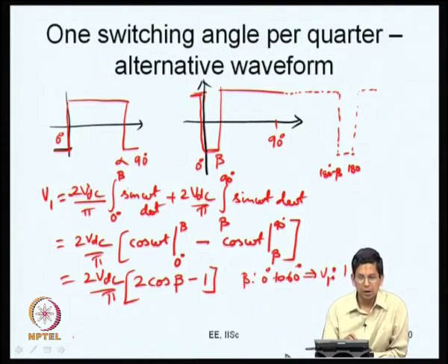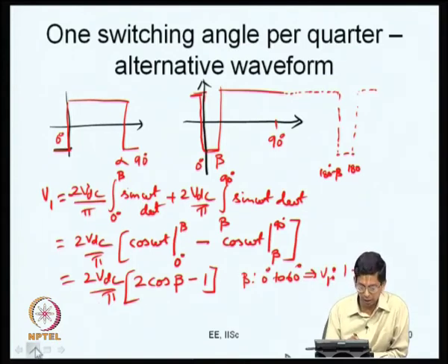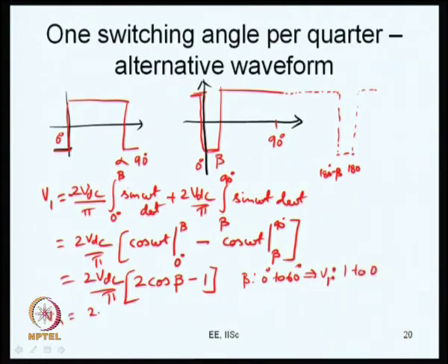and you have n omega t, you are going to integrate it with respect to n omega t. So, you will have an additional n coming up here for any Vn, you may have 2 VDC upon n pi, and you may have another cos n beta coming up here minus 1. This is what would be your corresponding voltages now.